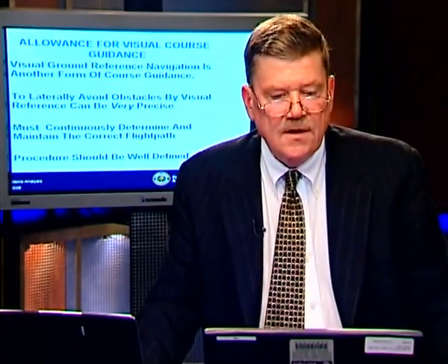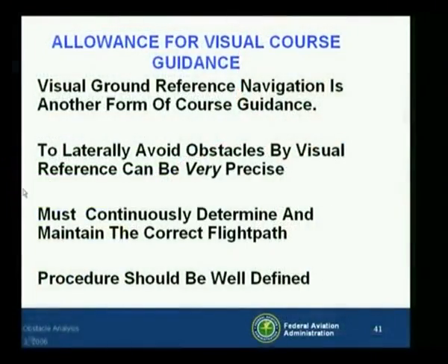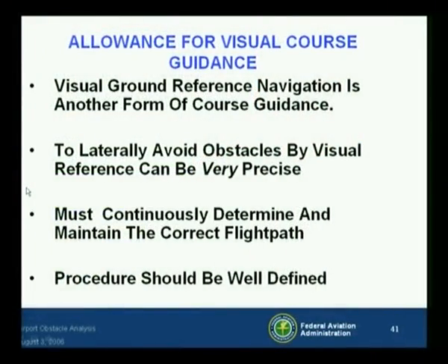That's a beautiful video. Lots of folks wonder if you can use these analysis methods in VMC conditions. And the answer is absolutely yes. Visual ground reference navigation is another form of course guidance. However, to take advantage of visual course guidance, a flight track analysis must be performed. Now, the ability to laterally avoid obstacles by visual reference can be very precise.